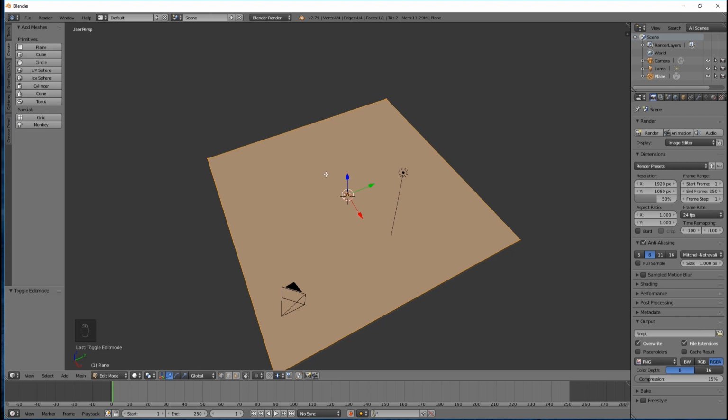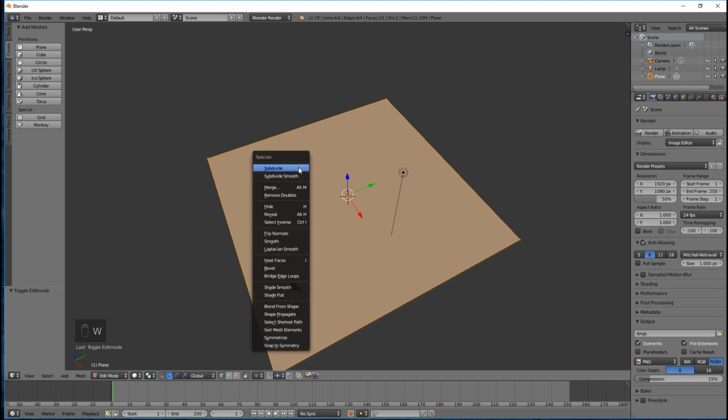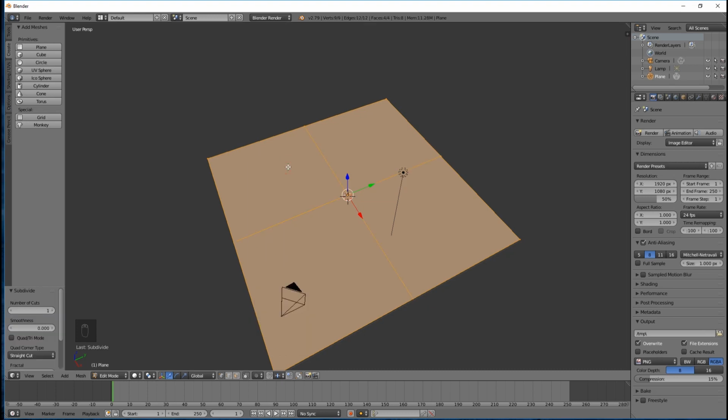That's kind of what we're going to do with the plane now. We're going to, if you like, add lots of creases that we can then pick at and pull at to be able to create the island. So with the mouse over the middle somewhere, I'm going to press the letter W on my keyboard, and that brings up the specials menu. And at the top, we're just going to choose that first option there called Subdivide.